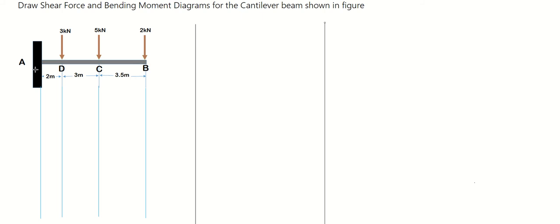In the previous videos we have seen a simply supported beam, where the loads are shared by the two supports appropriately. But here, in a cantilever beam, you can see this black single support, and this is the portion which is hanging. That means it has only one reaction. Whatever load is applied on the cantilever will be carried by this support only. So we need not calculate reactions here, because the only reaction is equal to the amount of load imposed on it.